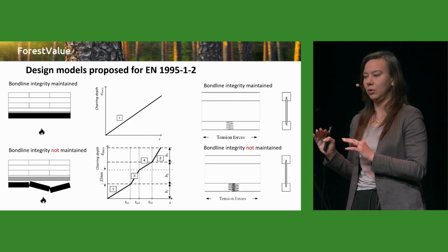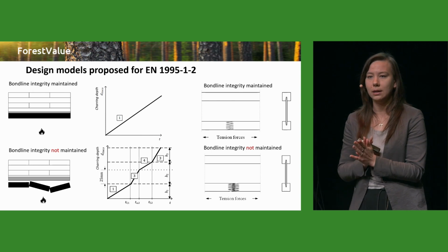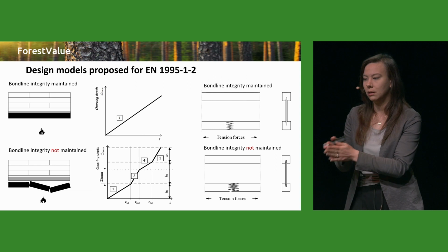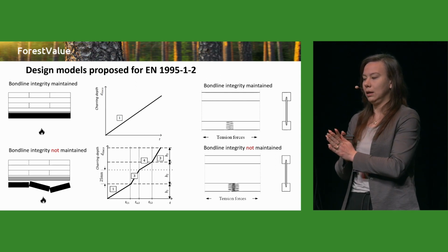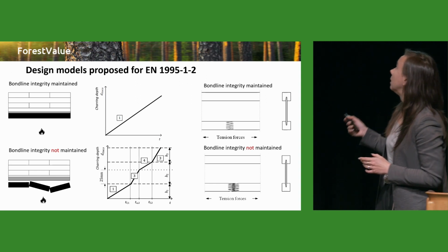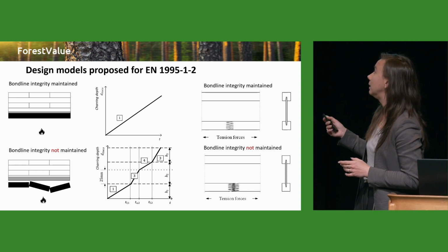First is that the bond line integrity is maintained. In that case, we consider that the adhesive does not soften faster than the char, and that means that we can calculate the char depth as a constant rate.